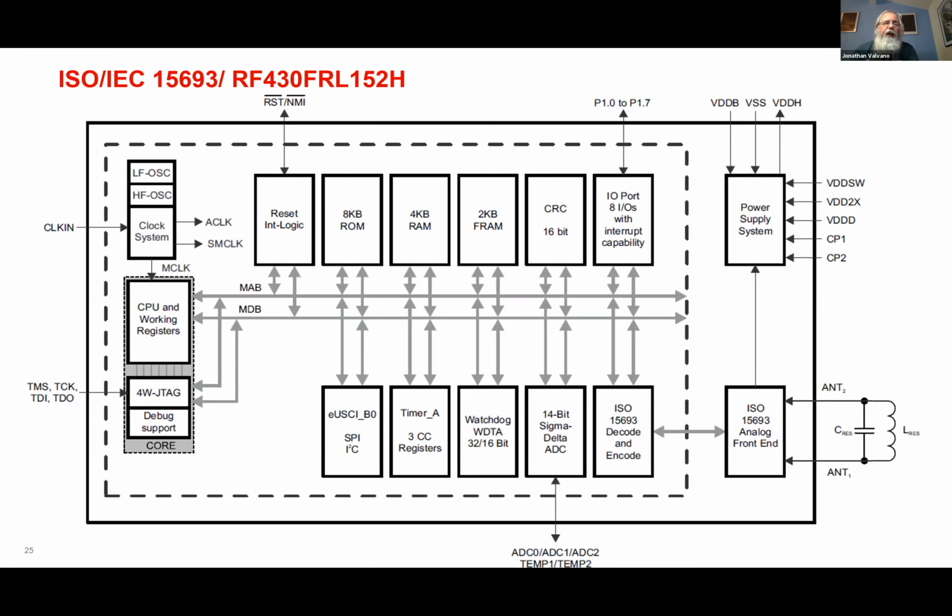Yeah, we tried programming these chips before we soldered them down, but apparently soldering erases the FRAM, so for this application we also had to build dongles so that after we soldered the chip on, we could program it. Okay, so this is basically just the mantra of the entire semester, and that is, okay, so I'm done.